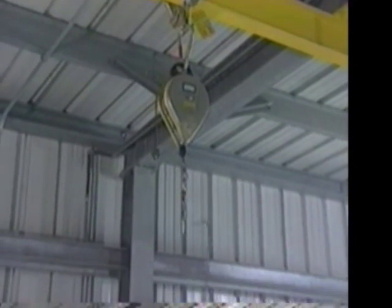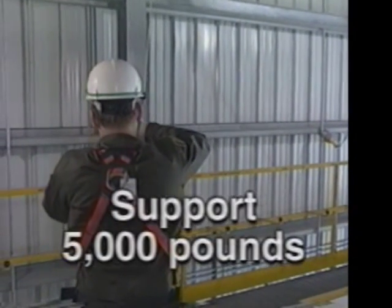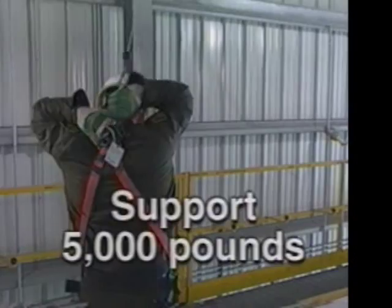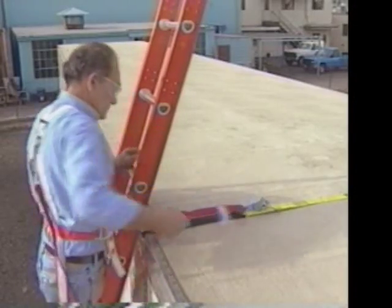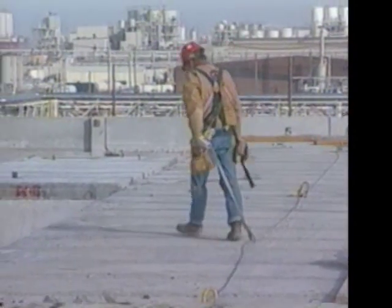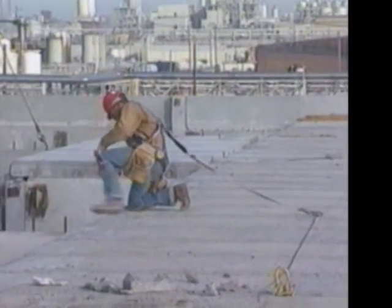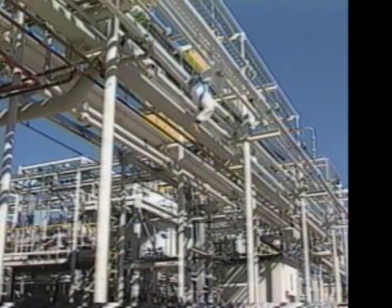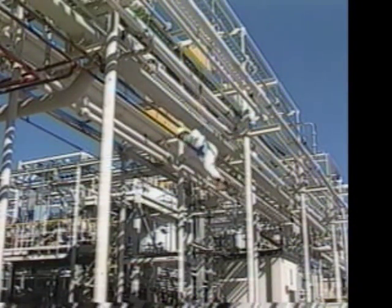The anchorage point is a secure place for attaching a personal fall arrest system. It must be able to support 5,000 pounds per worker attached and be independent from the means supporting or suspending the worker. You should be able to reach the anchorage point without exposure to hazards. The height of the anchorage point must allow the fall protection system to limit free fall to the shortest distance possible. A fall must not exceed 6 feet, nor allow the worker to contact a lower level.